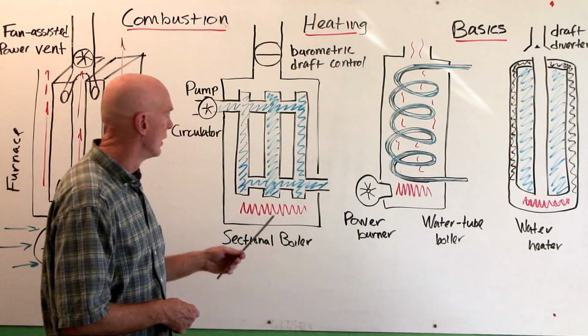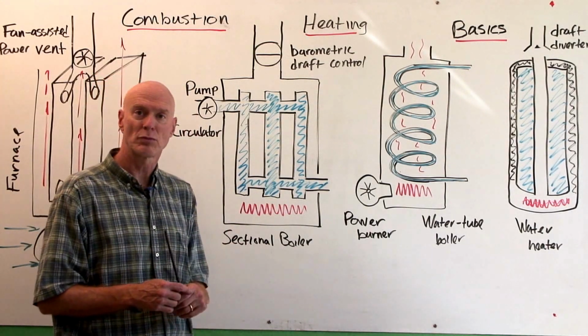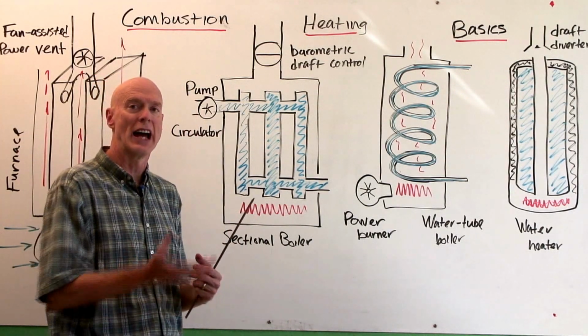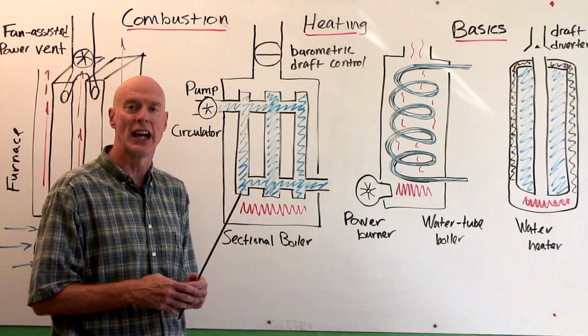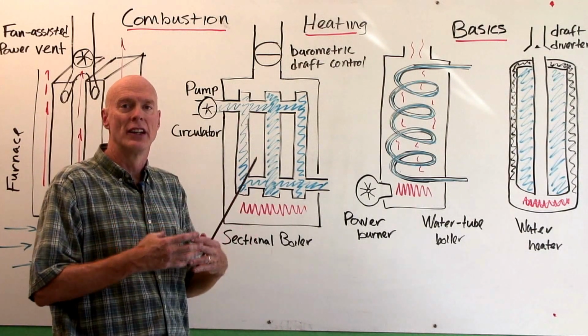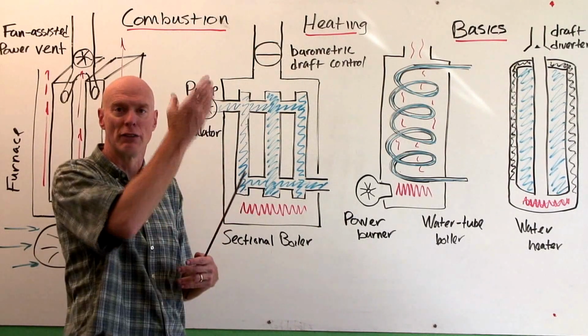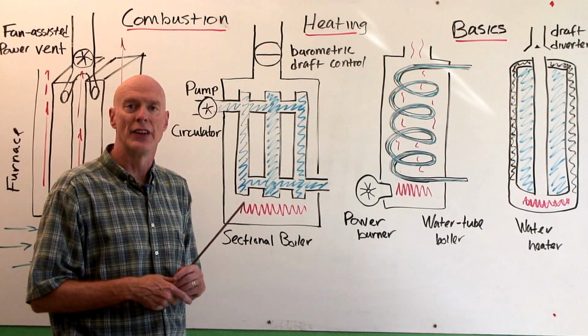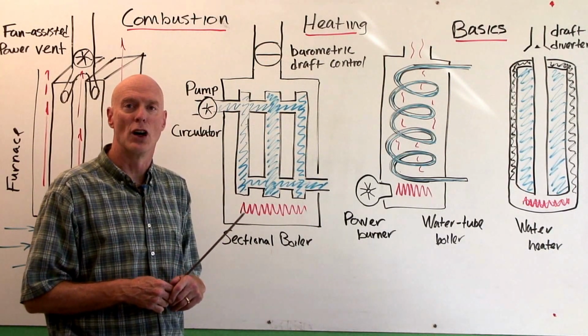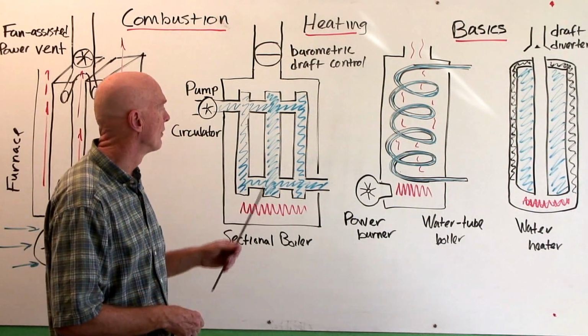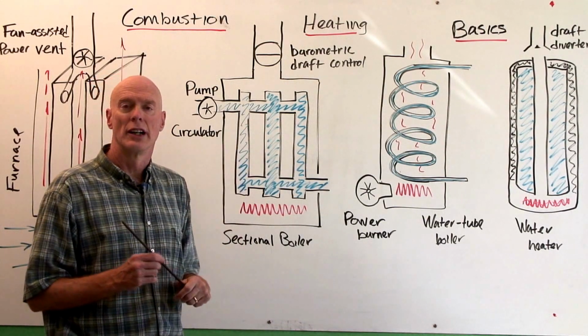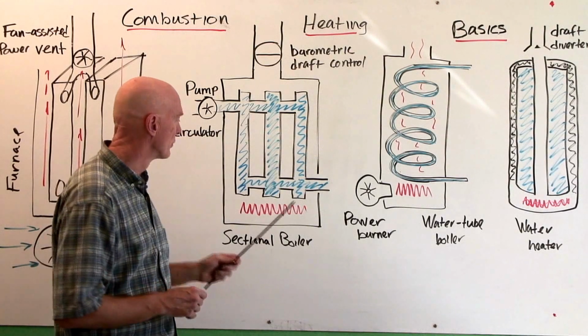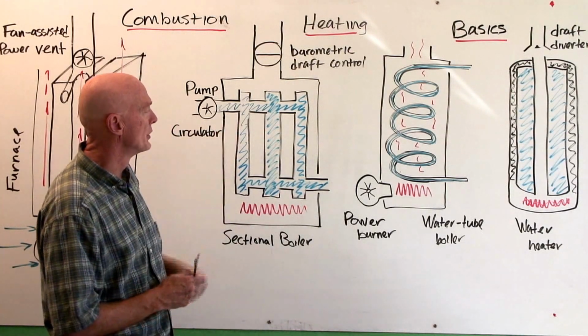It's really created by the flame. The flame powers its own gases out of the house. It heats the gases, they become hot, they're lighter than air, and they shove their way up the chimney, and they create a force called draft. And the draft continues to cause the exhaust gases from the flame to go out the chimney.